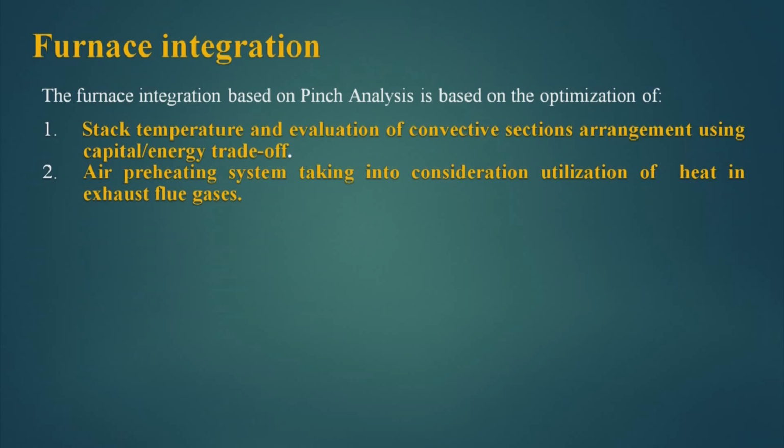The second part is that the air preheating system has to be designed, and we have to find out up to what temperature the air preheating should take place. This is also based on capital energy trade off, and we will fix what should be my maximum air preheat temperature and what should be my minimum stack temperature. These are two important parameters which have to be found out based on economic analysis when we are integrating a furnace.